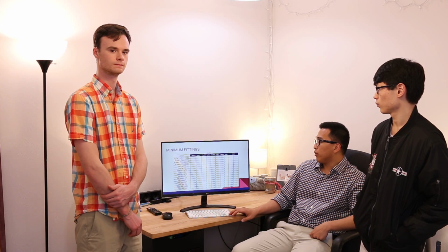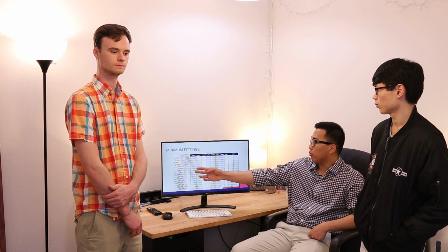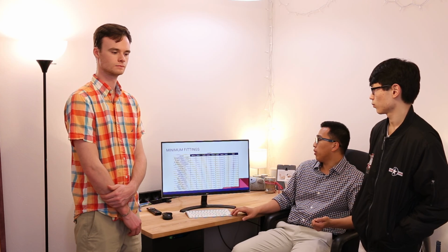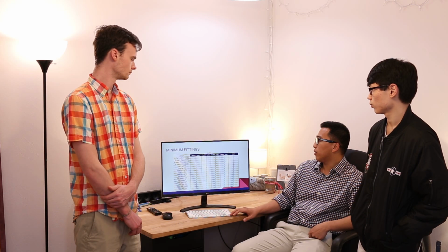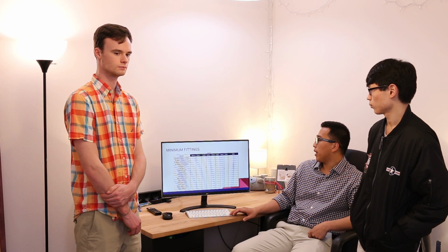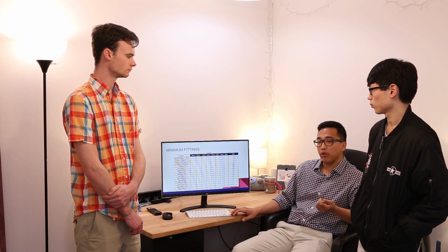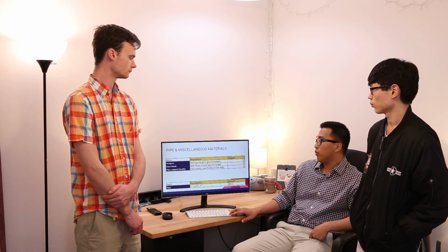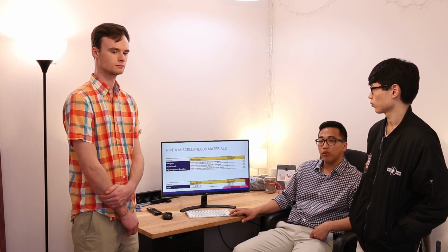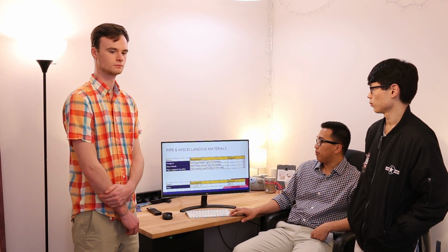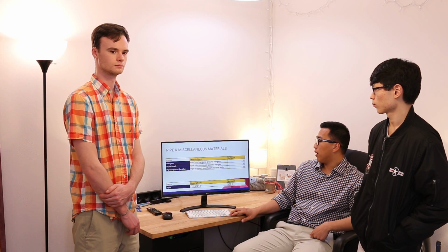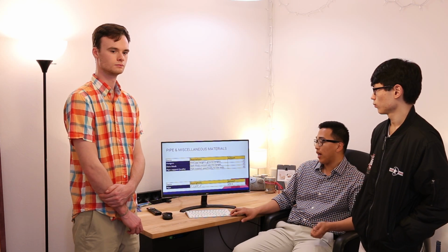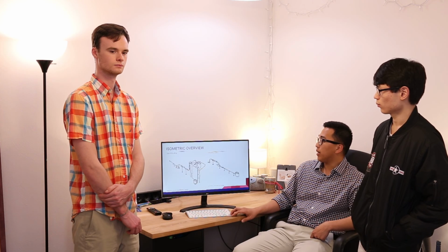For the minimum fittings, as Will mentioned, we tried to eliminate as many fittings as possible. The most used fitting is the 1 inch coupling, about 61 couplings. These 1 inch pipes go to the rooftop to tank 2, so that is the area where the most pipe is used, and that's why we have the most fittings there. For the pipe and miscellaneous materials, we use hangers, Durablock, and pipe supports to support the pipe. The pipe length is about 670 feet, combining the 1 inch, 1.5 inch and 2 inch diameter pipes.